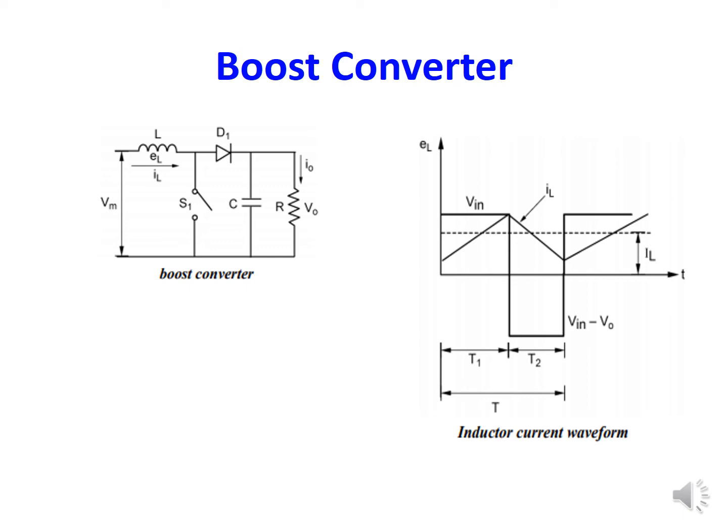When the switch is off, open, the input supply is now connected to the output via the series connected inductor and diode. As the inductor field decreases, the energy stored in the inductor is pushed to the output by Vin through the forward biased diode. This results in the induced voltage across the inductor reversing and adding to the voltage of the supply Vin. That is, it becomes Vin plus VL. Its corresponding waveforms are presented in the slide.